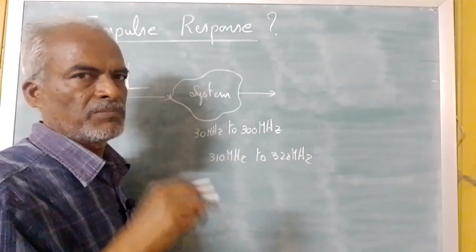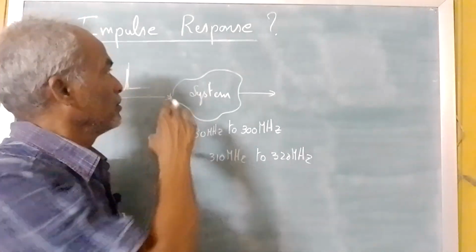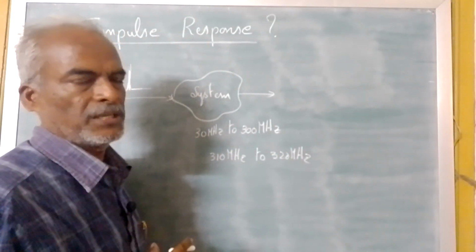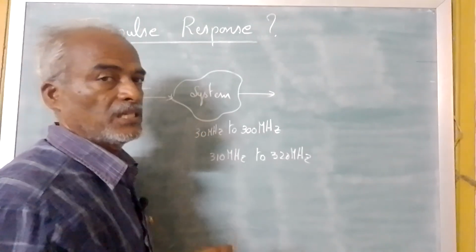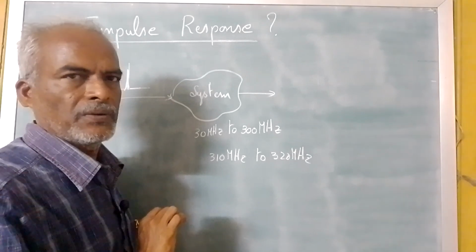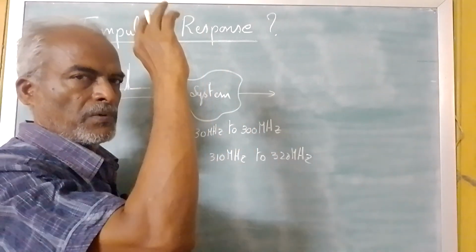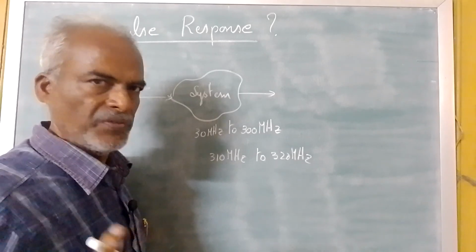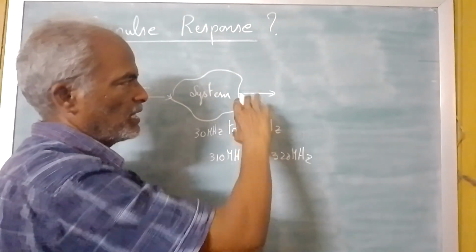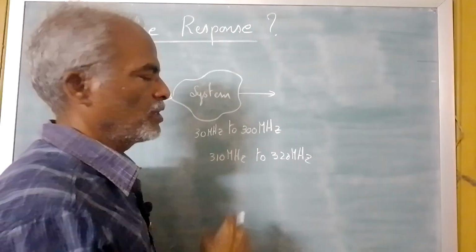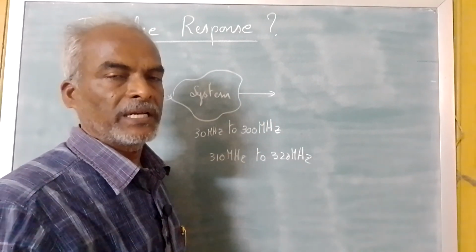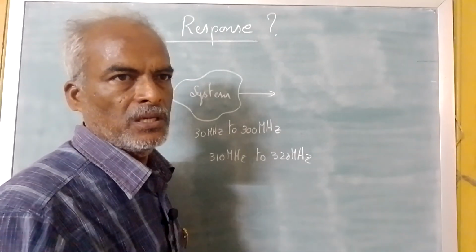That can be done only with the unit impulse. But generating this kind of signal is impossible, so you can use a very narrow pulse. That narrow pulse will have at most a wide range of frequencies, but ideally not infinity. So you can test the system, and if you connect a spectrum analyzer supporting the expected range, you can see all the response.